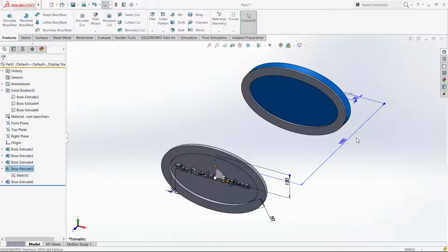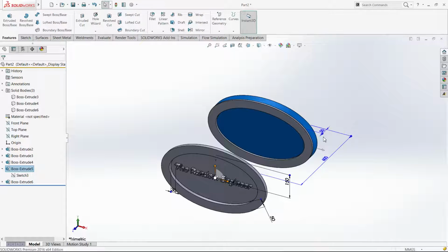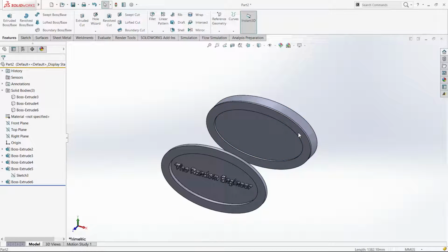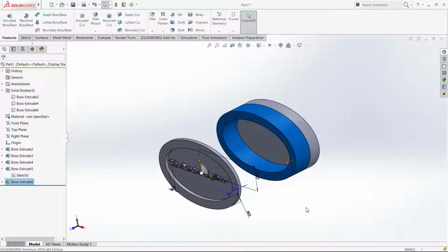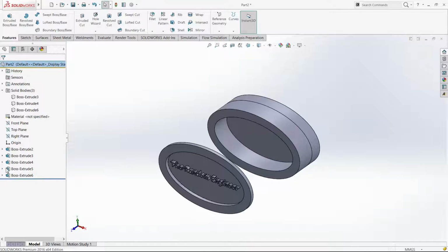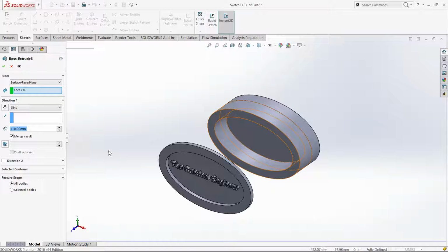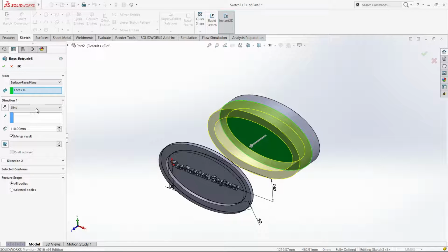So right now I said 600 millimeters offset and 50 thickness for that back solid. And if I double click on that oval, it says here there's 10, and let's say I want 110. And you can see there the difference between this up to next feature and just a blind dimension. So here we have more options.